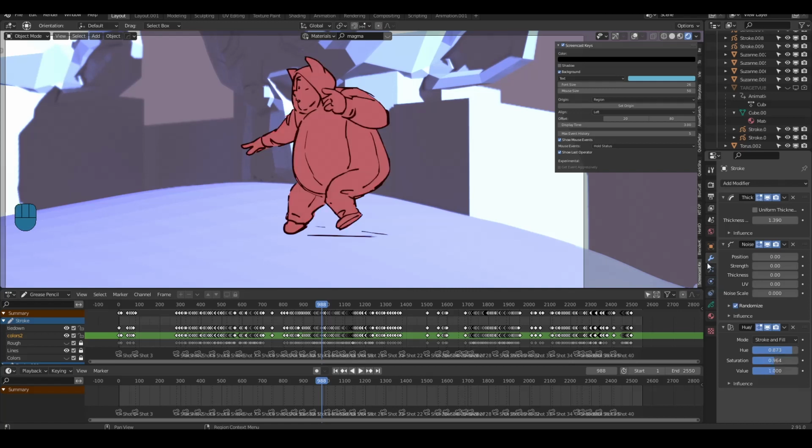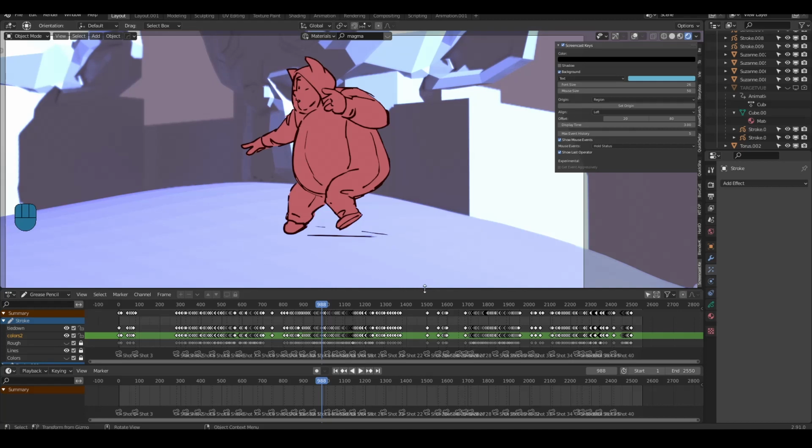The thing that doesn't work, but we're looking into it, is this: a couple of the effects modifiers don't work as they're supposed to in this thing, because they're kind of tied to the origin of the object, right? So blur and motion blur and the rim effects modifiers all seem to be related to the origin point. It doesn't mean you can't use them, it just means they don't work as easily as intended. I'll show you. Okay, so if we add a blur modifier to this, if I click use depth of field, it does work.